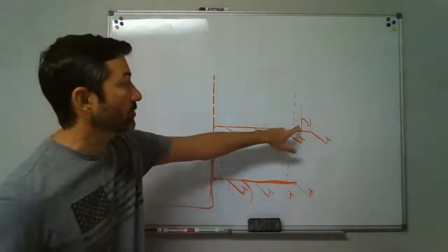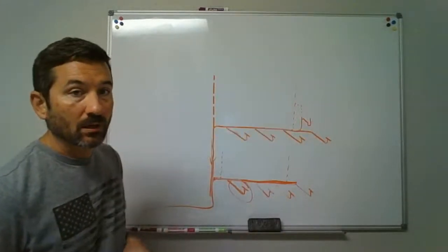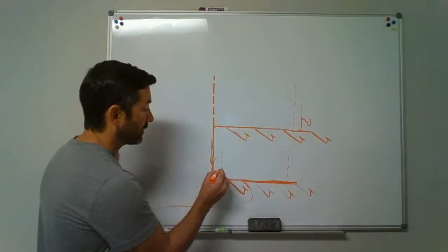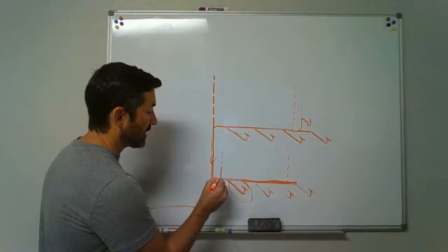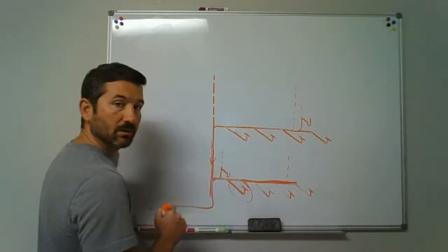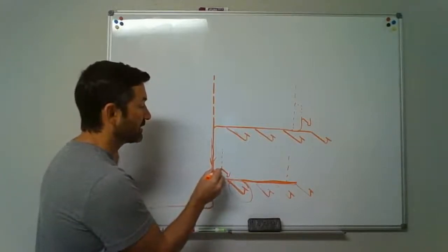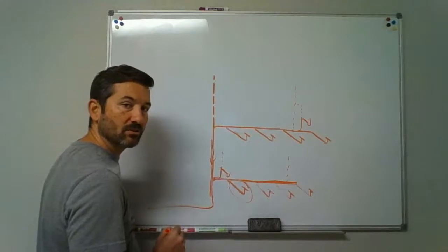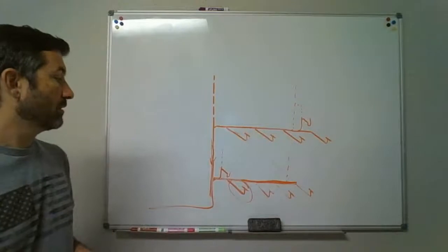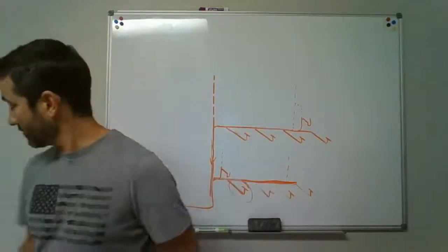You know how I told you we couldn't put a fixture and tie it to the circuit vent? Well, we can do it for the relief vent. So if we come down here, I can make that part a drain, and I'm going to come out with a sink. Or I could put 2 sinks. I can have 4 DFUs tied to this relief vent, and it still serves as the relief vent and is okay. So that's permissible right there. There's the circuit vent. There's the relief vent for the circuit vent.